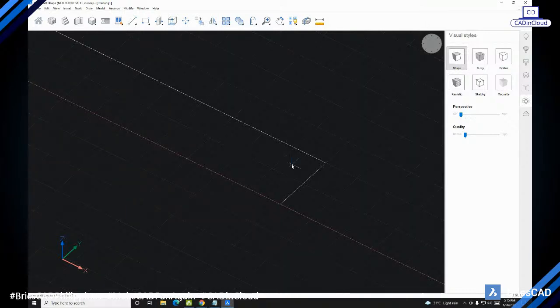So it is going to ask first for the distance one, or first entity distance. So I will put 100 millimeter. So 100 for the distance one. Then for the distance two, I already have the 100 value here because I entered 100 in the distance one. So you can simply press enter, or if you're unsure, you can type again.